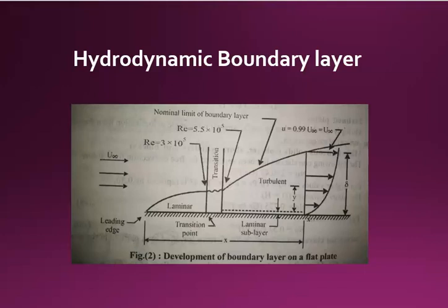It is 0 at the leading edge of the plate and increases as the distance x from the leading edge is increased. This may be attributed to the viscous force, which dissipates more and more energy of the fluid stream as the flow proceeds. Consequently, a larger group of fluid particles is slowed down. The boundary layer growth is also governed by parameters such as the magnitude of the incoming velocity and the kinematic viscosity of the flowing fluid.